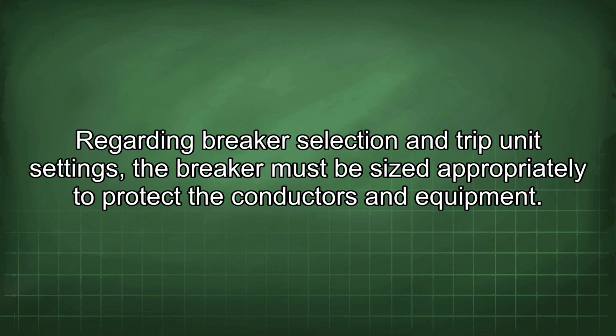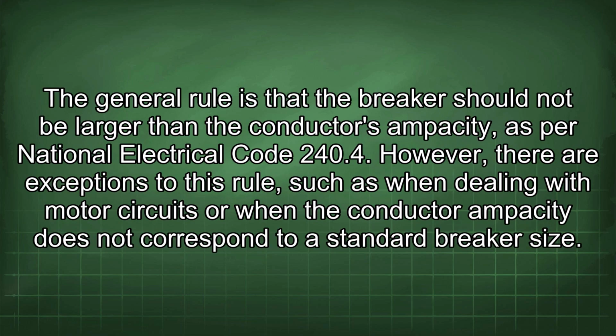Regarding breaker selection and trip unit settings, the breaker must be sized appropriately to protect the conductors and equipment. The general rule is that the breaker should not be larger than the conductor's ampacity as per National Electrical Code 240.4. However, there are exceptions to this rule, such as when dealing with motor circuits or when the conductor ampacity does not correspond to a standard breaker size.